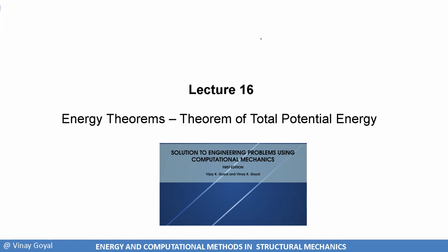Then I moved to Timoshenko theory, because Euler Bernoulli beam theory is only good for thin and very long structures. But Timoshenko beam theory is very good for thick structures, meaning the length can be short compared to the thickness. And in fact, we demonstrated that Timoshenko beam theory gives you, again, Euler Lagrange equations, and that theory is more general than Euler Bernoulli beam theory. And again, there are screw ups, because Timoshenko beam theory tells you that the shear stress through the cross section is constant. We know from mechanics of materials it's parabolic. Guess what? That is a consequence of the assumptions we made. But calculus of variations did the best it could.